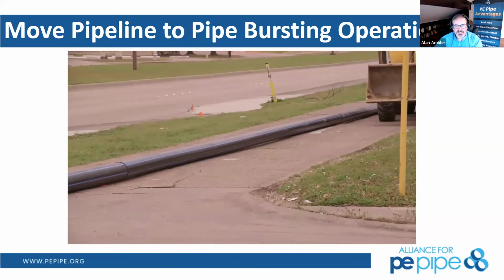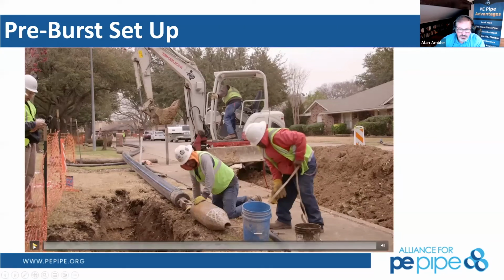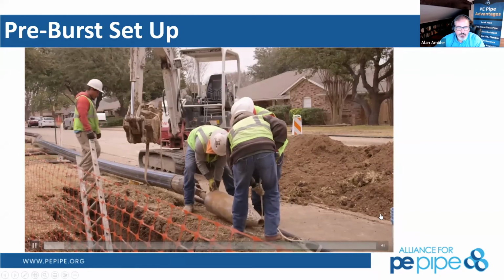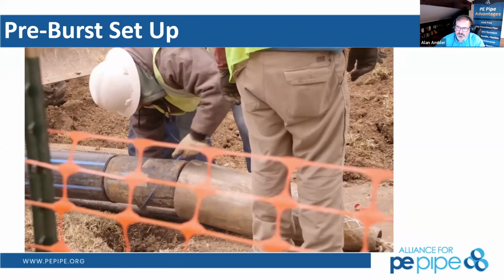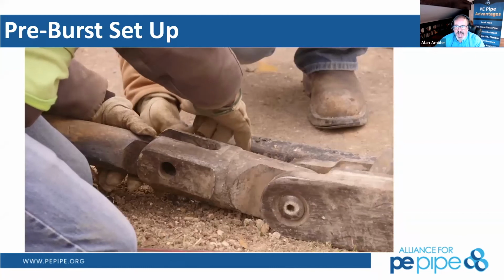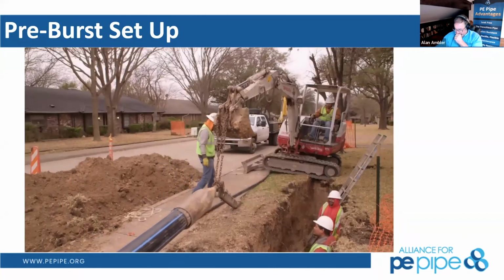Great. And Rusty, that gave me just long enough to think of the stat I was thinking of, and it's 3 to 5 feet per minute, giving us a 500-foot pull in about an hour time frame. So it can pay out all of the rods and cable in that hour, 45 minutes to an hour beforehand, and then the actual act of bringing this pipe bursting head, the expander head, back through can take that hour as well.